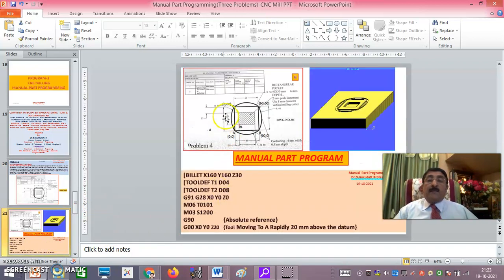Now you see here, carefully, first I have written the profile again here. A, B, C, D I have written. I start from A, 0, 0. This is 60, 0. 60, 60. 0, 60. Once I have written this, the things will become easy. And as I said, this is an arc anti-clockwise, this is an arc anti-clockwise, this is an arc anti-clockwise.